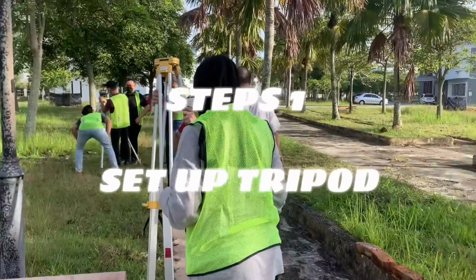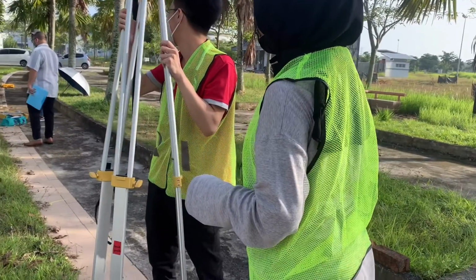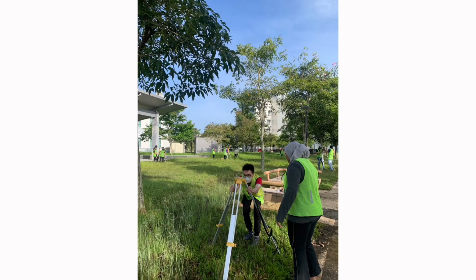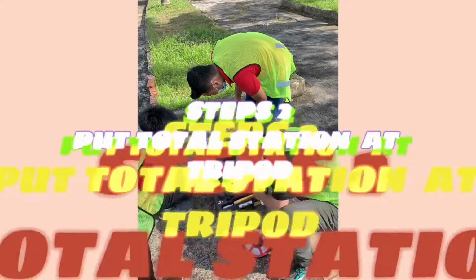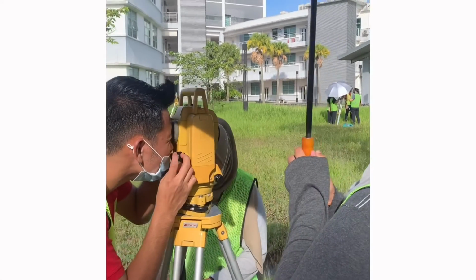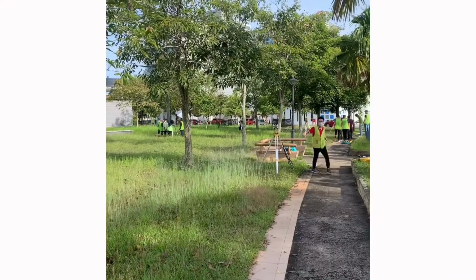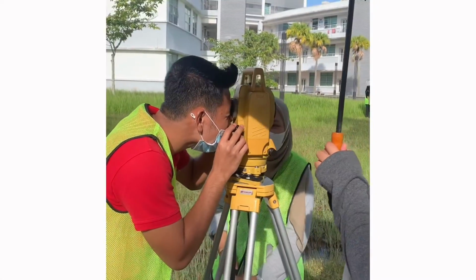Step 1. Set up tripod. Set up the tripod on the station, open its legs and regulate the height so that it is approximately precise, and regulate it so that the ground seems flat as observed. Step 2. Put total station on tripod. The total station device is positioned on the tripod, secured with a centering screw. While pressing the device with the other hand, insert the battery inside the device before leveling.